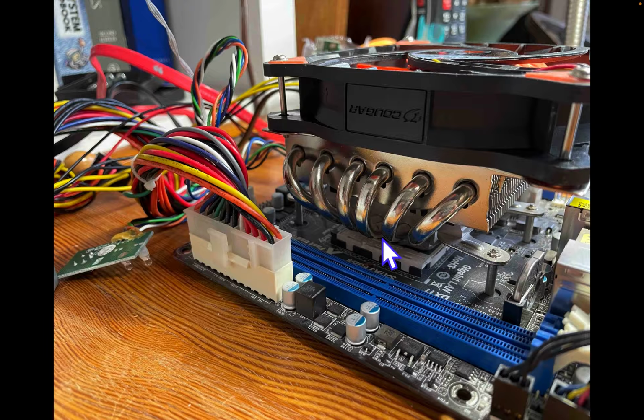Orange wires carry 3.3 volts. Red wires carry 5 volts, and yellow carry 12. Blue wires are negative 12 volts, and that gray wire going into pin 19 is positive 5 volts and carries a power good signal to the CPU every time the computer is first powered on.